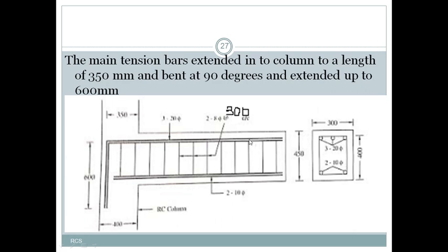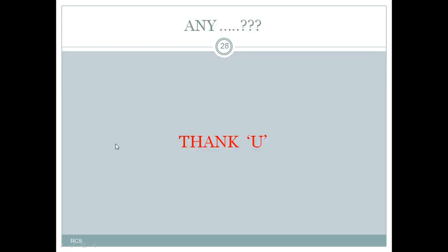So the stress induced due to the imbalanced force will develop bond stress here. That bond stress is the stress induced at the interface of your steel bar and concrete that will transfer the equal amount of load onto the concrete. So that is the purpose why we are providing LD or development length into this column. So this is all for today's lecture. Thank you.